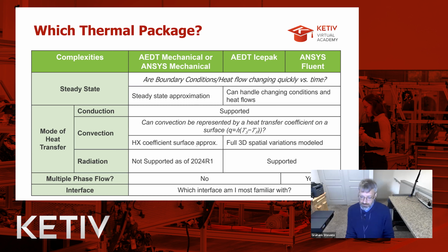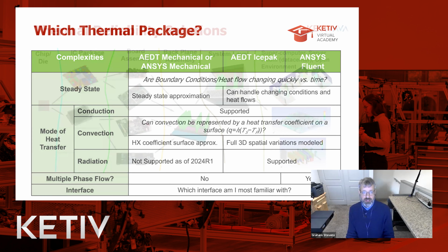If you can make that, please use Mechanical. It can be faster sometimes than IcePak as well. But if not, then jump to IcePak to handle those changing conditions, heat flows, and full 3D spatial variations. So this is just a brief overview of which thermal package you might want to use.